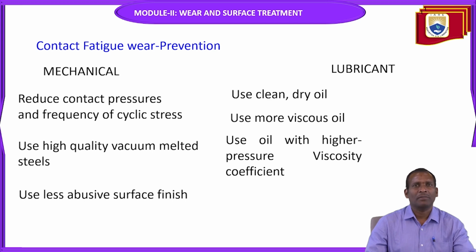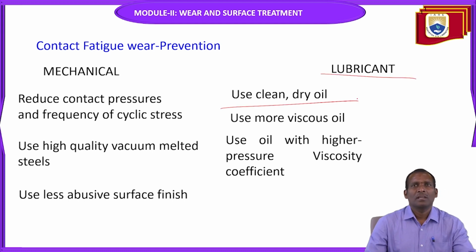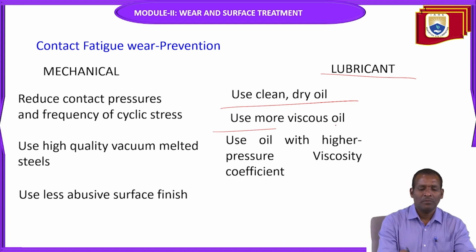Use high quality vacuum melted steels. Use a less abusive surface finish. From the lubricant point of view, use clean and dry oil. Use more viscous oil.